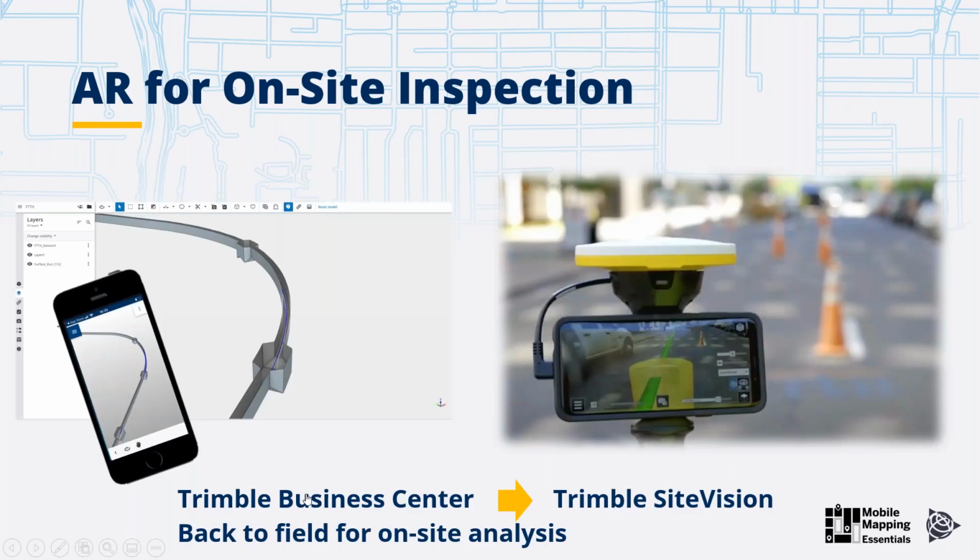The 3D model, which is created when a trench template is applied to the mesh, can also be exported, for example, to Trimble Connect. And the interesting thing is that if the company, for example, owns some SiteVision kits, this 3D model can be transferred directly to the field with the SiteVision kit. And then it's possible to make use of augmented reality to visually check how the new installation, how the trench, would look like in real, directly in the field.